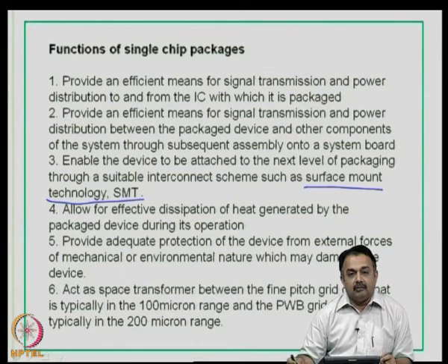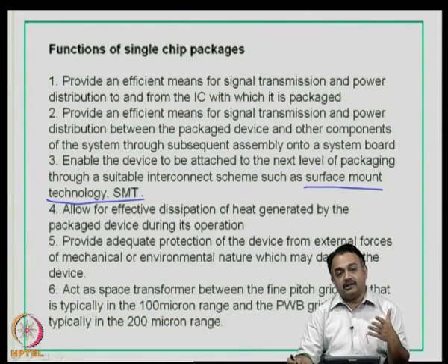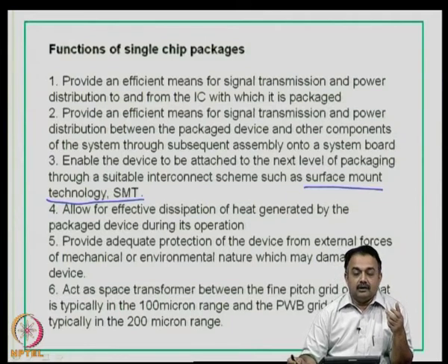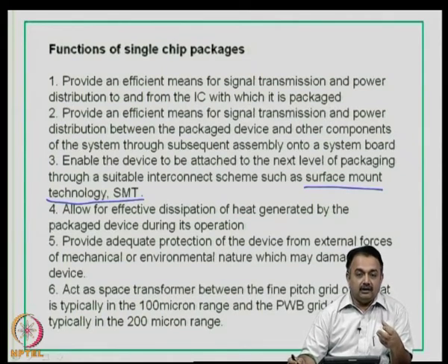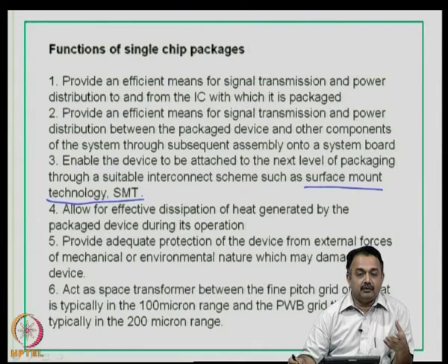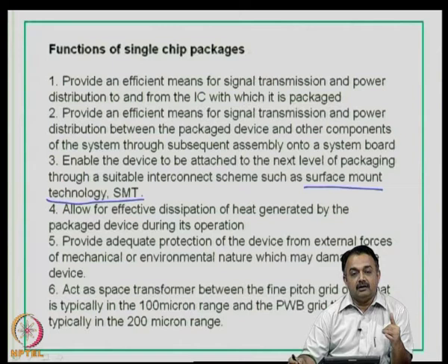Then the package should allow for efficient and effective dissipation of heat when the package is powered up, right. So, when the package is powered up through the circuit that you have designed, there will be heat generated from the device, from the active device. And how are you going to take care of it? Partly the package material has to take care of it, to dissipate the heat from the silicon die through the package material to the environment, and that happens through the system level printed wiring board.